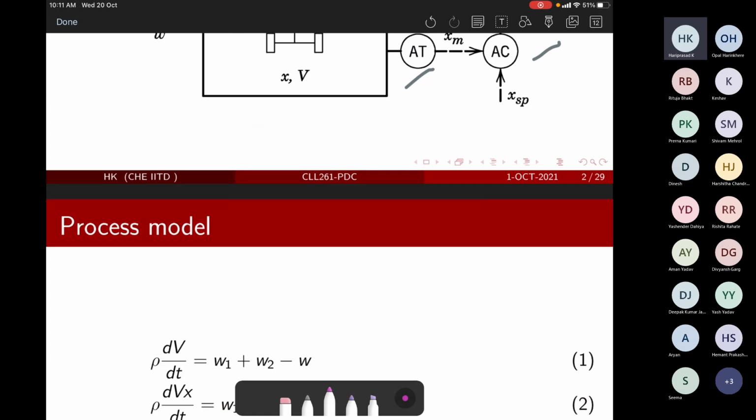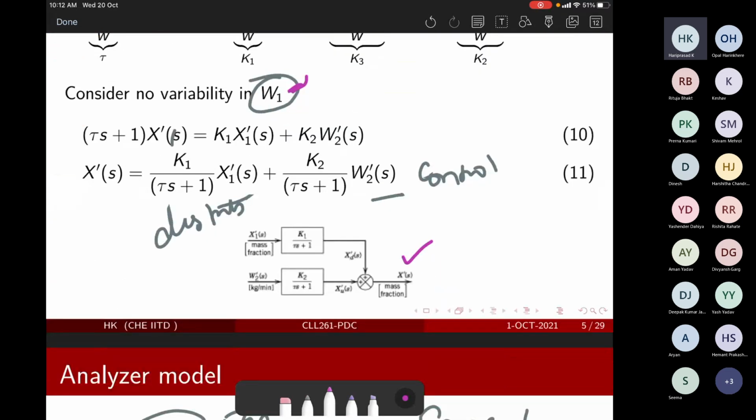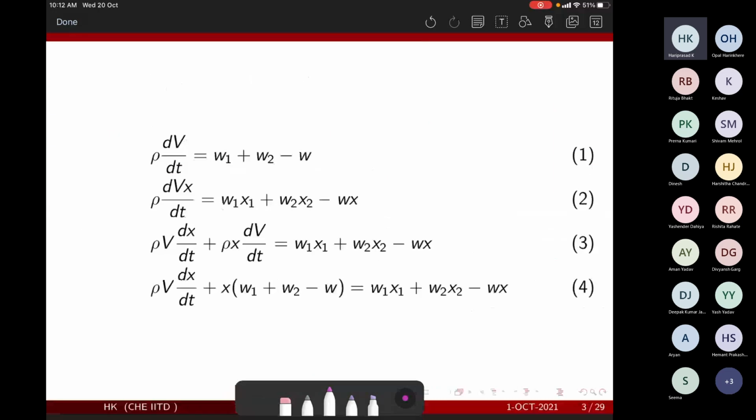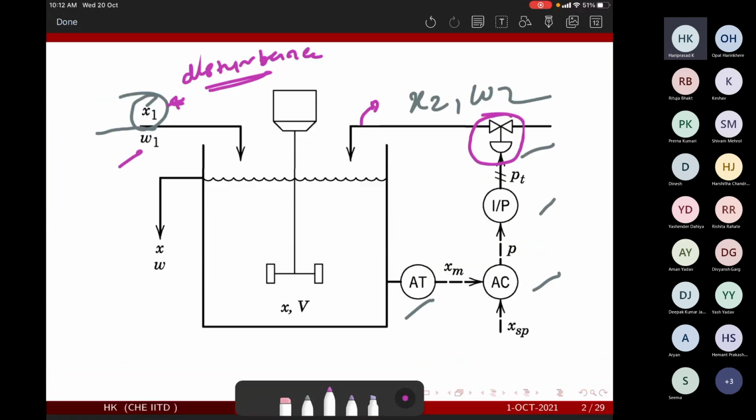So this would change. Your overall transfer function should technically contain two components: a disturbance component and a relationship with respect to the manipulated variable, and its total summation is your output, because your overall output here contains this, which is the control or manipulated line.